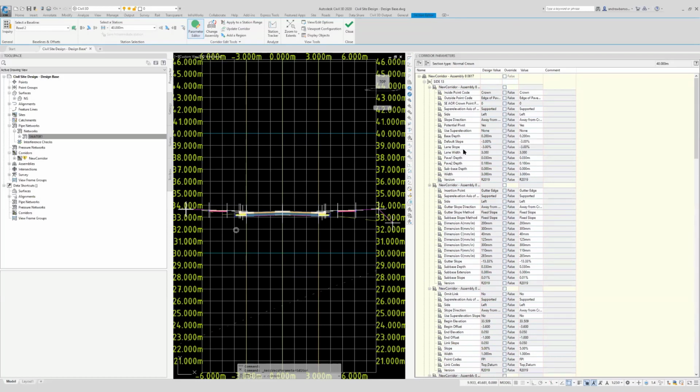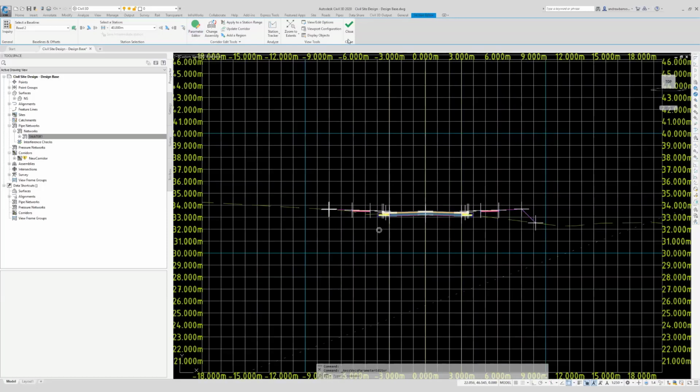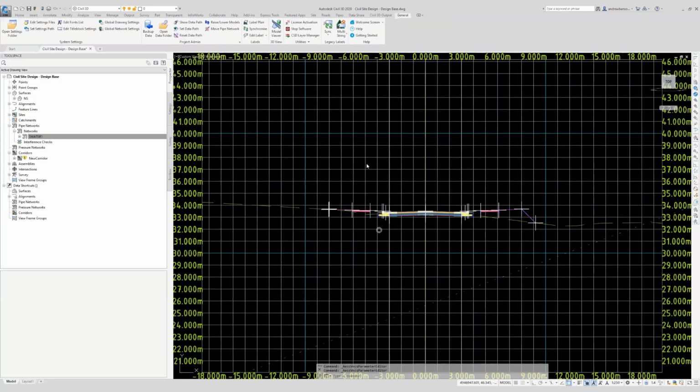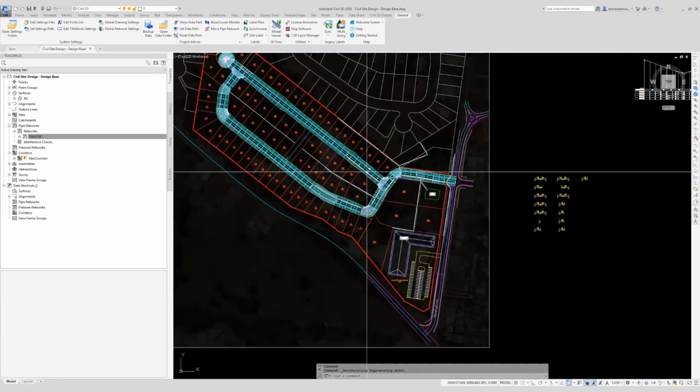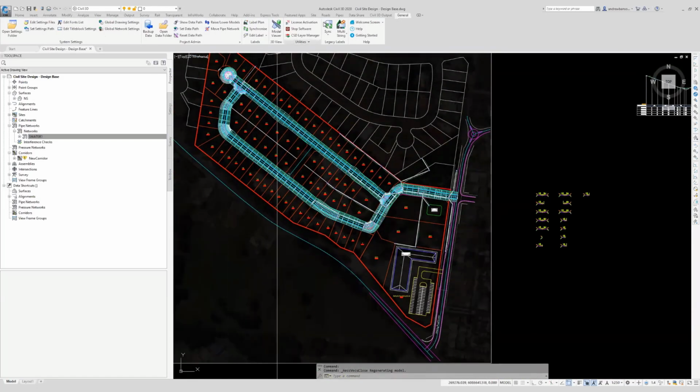For whatever reason, in order to get the slope, because maybe you added variations or changed the width, we might do that by adding a parameter override. Parameter override is a little bit messy, so we like to use targeting as much as possible.